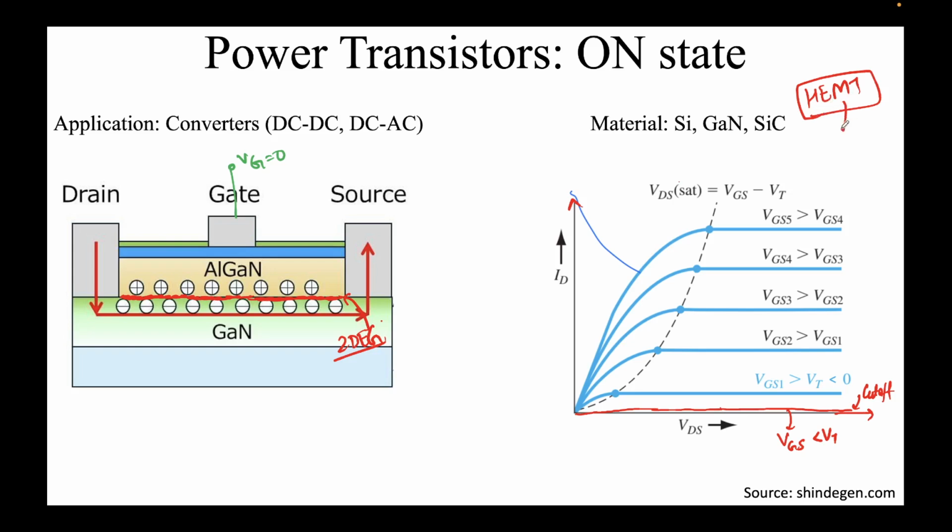I'll say that the key term here we're getting is mobility, right? Why is the mobility of electrons high? The reason is that in silicon, when the inversion layer is between the oxide and the silicon interface, there are various ways of scattering of that electron. Impurity scattering, because silicon is doped. If you recall, it was a p-type silicon for an N MOSFET, correct? So there are some dopants which will scatter the electrons. Second, this is an interface between silicon dioxide and silicon. Although it's nearly close to ideal, there will still be some scattering, right? And there can be some defects that might arise on that interface.